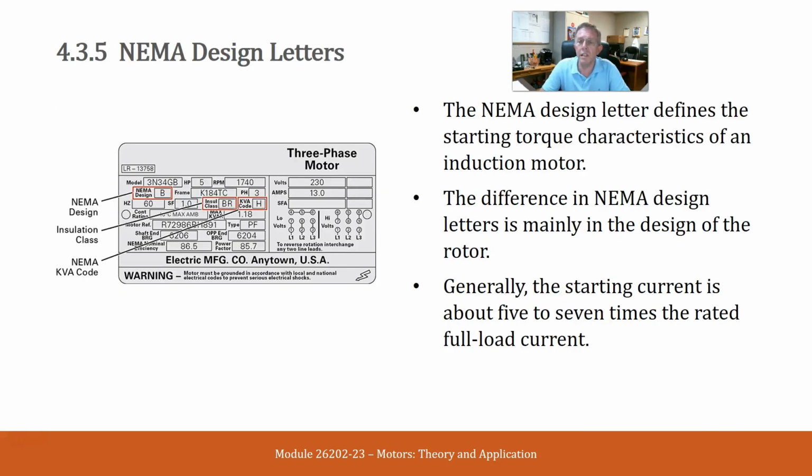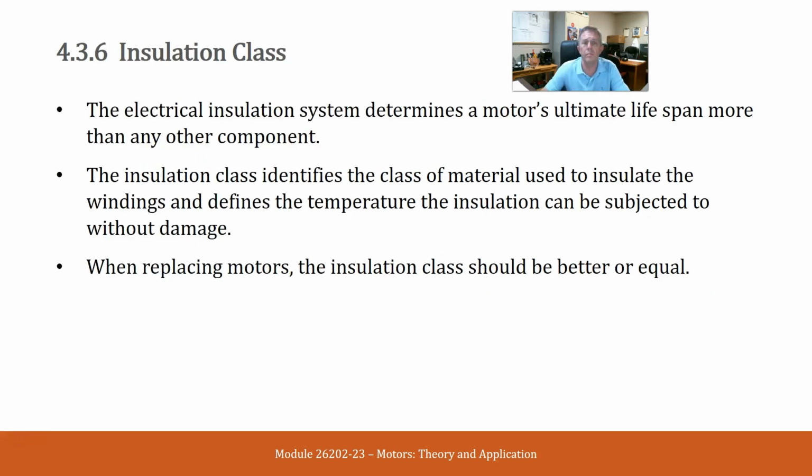The NEMA design letter defines the starting torque characteristics of an induction motor. The difference in NEMA design letters is mainly the design of the rotor. Generally, the starting current is about 5 to 7 times the rated full load current.